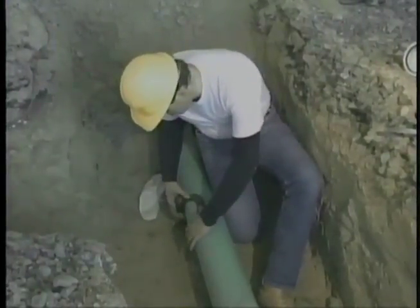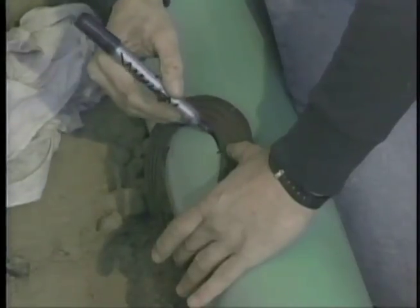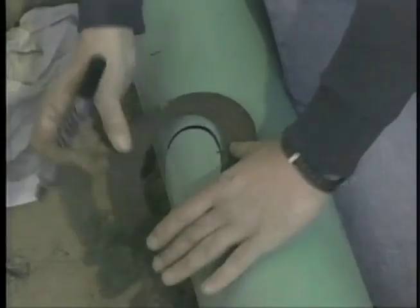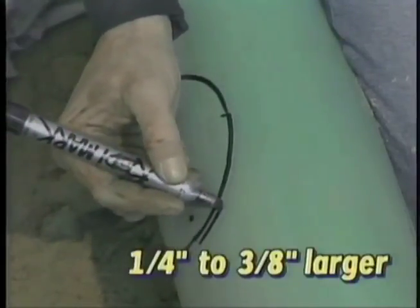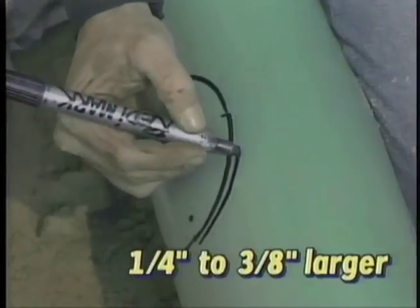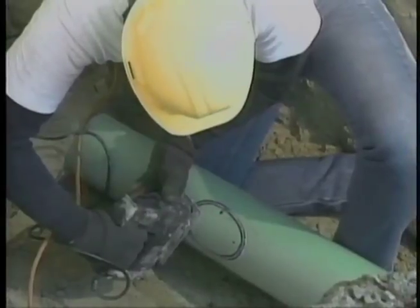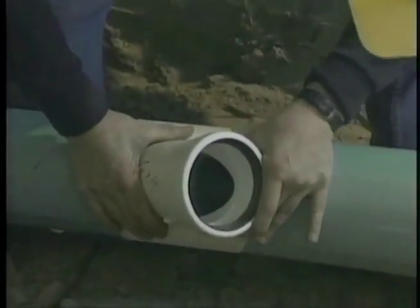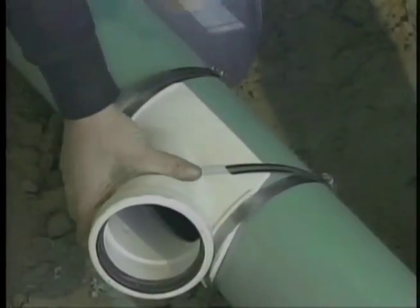To install the saddle, mark the diameter and location using the inside of the gasket or the saddle as a template. Mark the cut line approximately 1/4 to 3/8 of an inch larger than the diameter of the saddle. After cutting the hole, attach the gasket to the saddle and mount to the main line by either gluing or tightening the clamps to achieve a sealed and secure fitting.